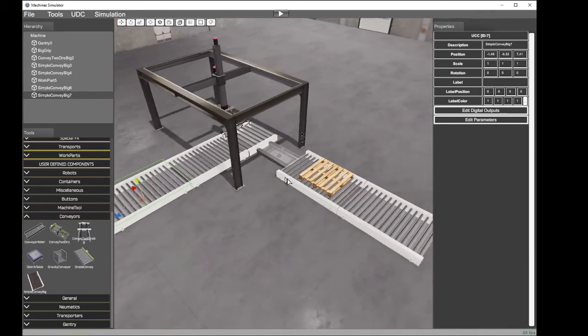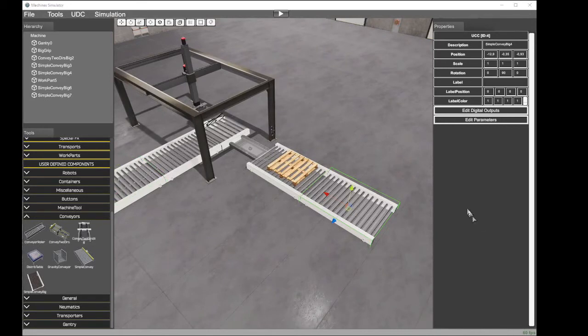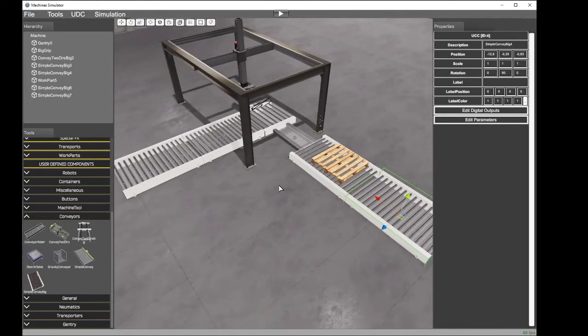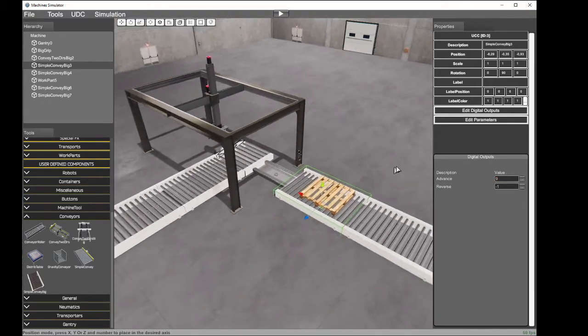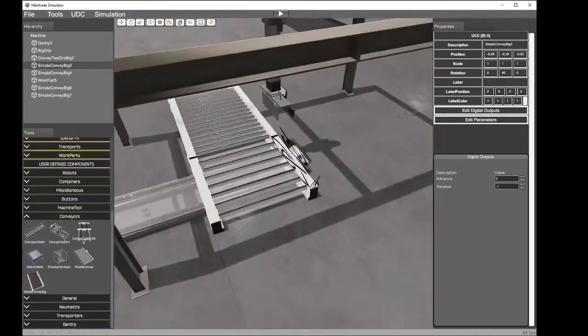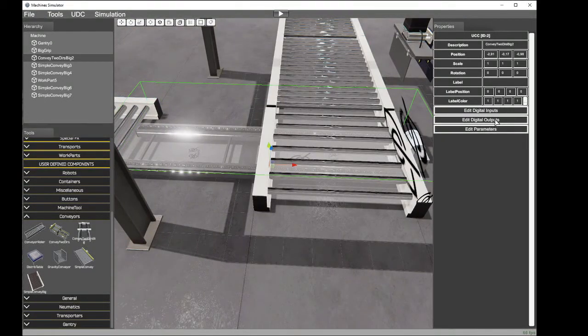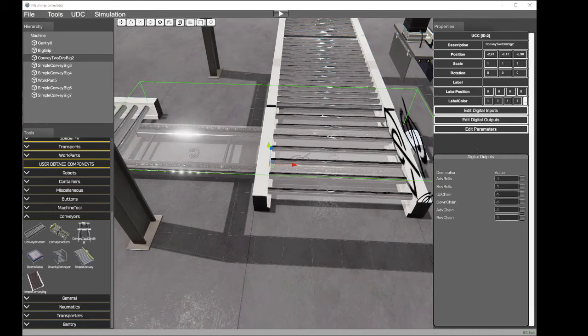We must configure the PLC outputs. So we start, for instance, with this. It's a good idea to have an IO list to have everything listed. In my list, I have the 9 PLC outputs. The same for this. For the 2D conveyors, I'm going to program the following PLC outputs. Advance rollers, the 4; backwards to upper chain 6; down chain 7; advance is not necessary; and to move the chains the 8. Okay.